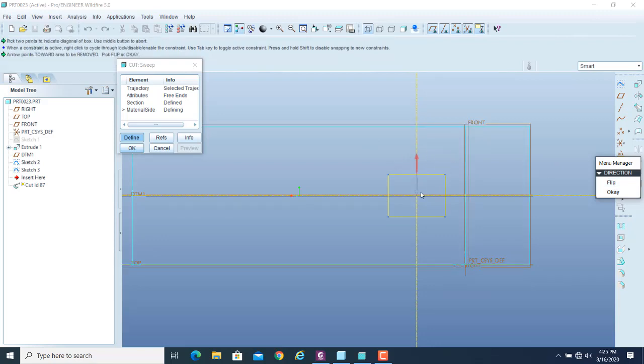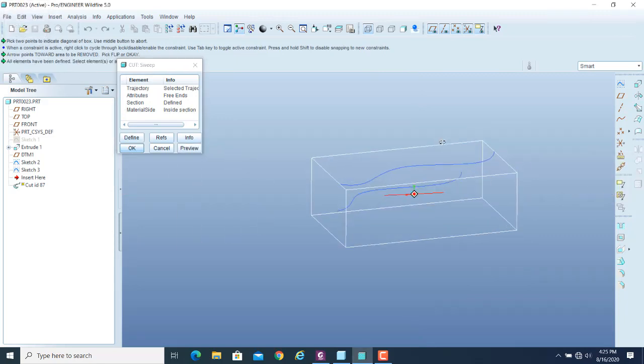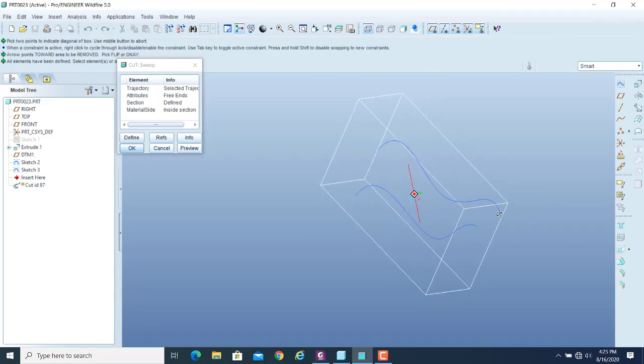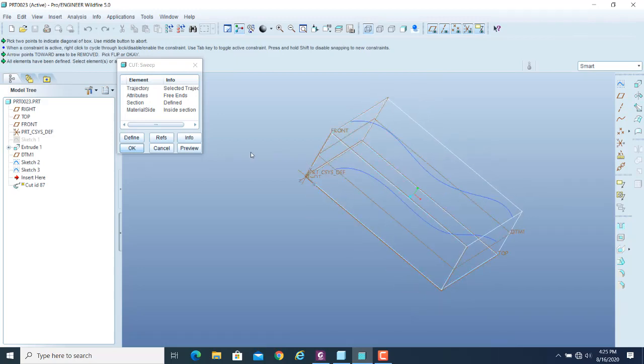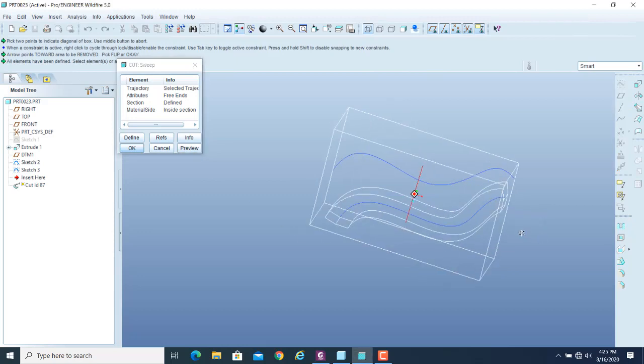So obviously you have to go for the internal region, otherwise you can flip the external region. So if it is a thickened part, or for example consisting of 3 or 4 multiple entities, you can always use the flip option. So I will in this case remove the internal region and will click the OK button. So now if you click on the preview button, you can see that it has generated that particular rectangle along the trajectory.